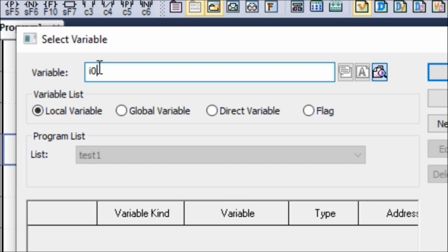It is very important to mention that in compact PLCs, you must enter the value 0 here without exception. However, in modular PLCs such as the advanced XGT series, this number can be different. That is to say, if our PLC happens to be a modular PLC and we connect an additional rack to it, then the numbering might change accordingly. We can enter the number of that rack here. But since our PLC here is compact, in all compact PLCs, we always set this value to 0.